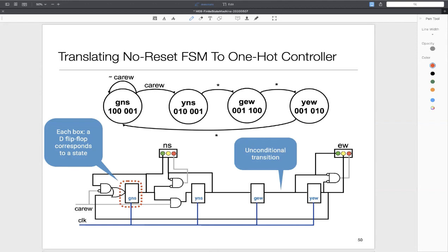And there is a third one. Sometimes these systems are remote, particularly a traffic light controller, and if they hang, you're not going to send a person to manually reset it. So usually they have a circuit called a watchdog timer. What these watchdog timers do is keep checking, is the system stuck? And if the system is stuck, they reset the hardware automatically. So that's the third one. These are some examples of where the reset signal may come from. Okay, thank you. Manual, watchdog, and right after power up.